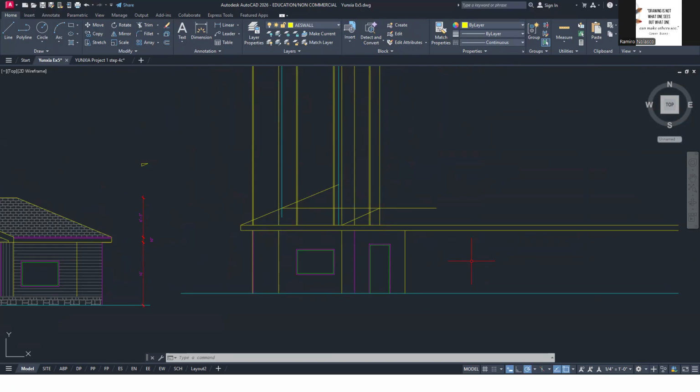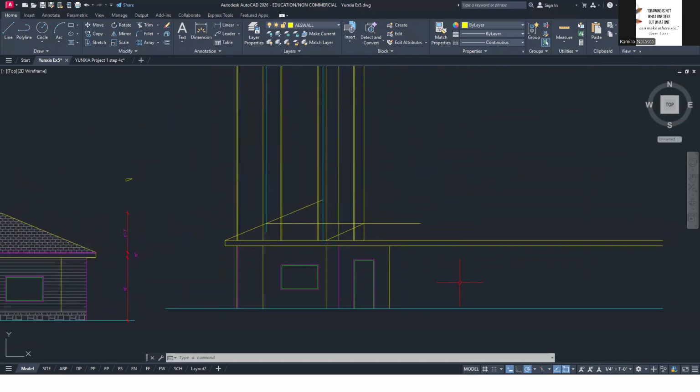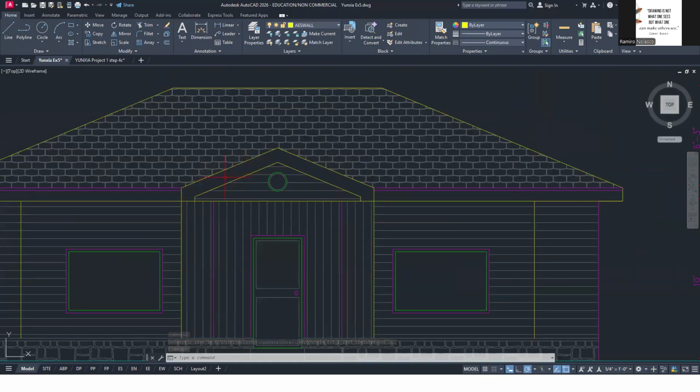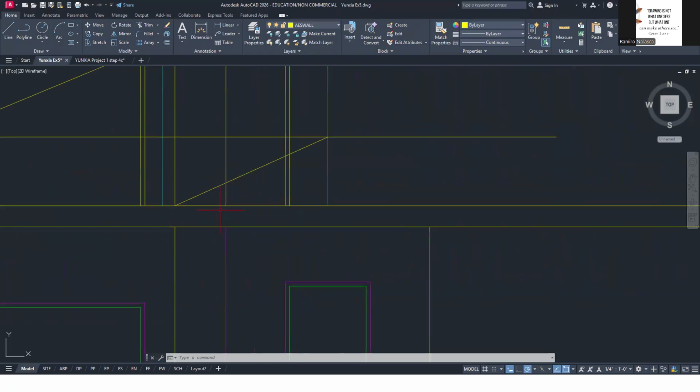And any other item? That's good actually. Good thinking. Why not just project that other now, next from here I can mirror, I think. Anything I should do first before mirroring? Oh, this one here. Hatch I'll do after. So this one I would like to do. It's up to you how far this fascia or design will look like. So I can maybe do 10 inches as well. So offset by 10.